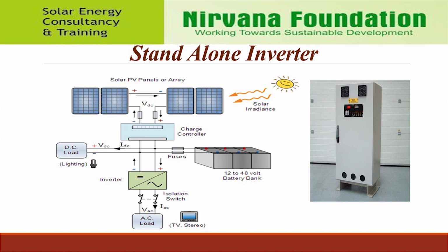Standalone inverter or off-grid inverter is designed for remote standalone application or off-grid power system with battery backup where the inverter draws its DC power from batteries charged by PV array and converts to AC power. Standalone inverters provide variety of size and output waveform depending on your applications.